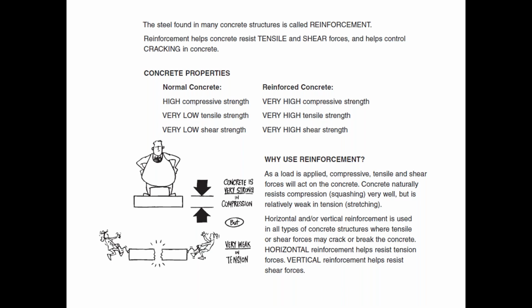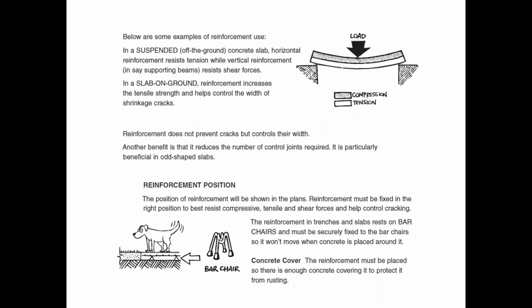All right. And here's a good example, at the top right-hand side there, everybody. There's a little picture of a concrete bridge, and just pretend there's a big truck or something driving over it, right in the middle. Now, if you look at that bridge, we've got two sorts of loadings on it. On top you'd have the compression, which the concrete's very strong at, but on the bottom side of that, you would actually create tension, and the concrete's trying to break itself apart. So hence why we put the reinforcing steel in the first place, is that helps handle the tension part of the process and gives it more strength.